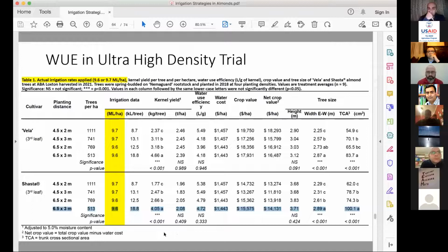There could be other soil moisture sensors that tell you the volumetric soil water measurements in your root zone. Typically the soil moisture sensors are used to quantify the volumetric water percentage in the soil. So that's the method that I would recommend.